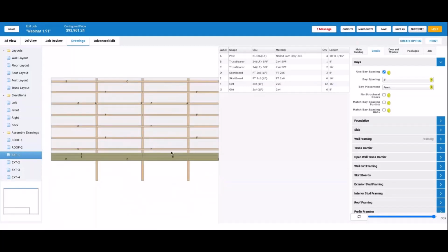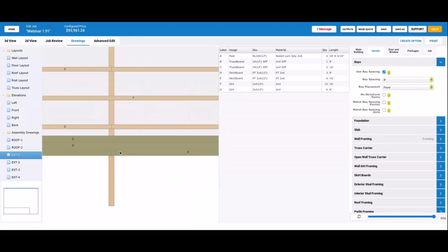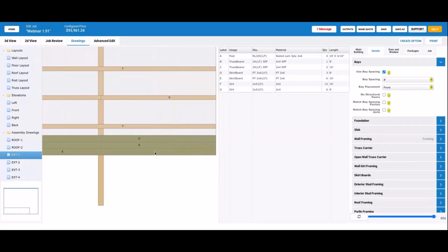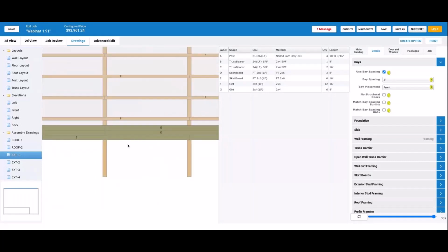Makes sense. And that's because they're actually piling dirt up against the bottom 2 skirt boards. Brandon said they treat the bottom 2 rows because they're going to pile dirt up against them. But the third row is untreated because the steel actually stops on that third row.